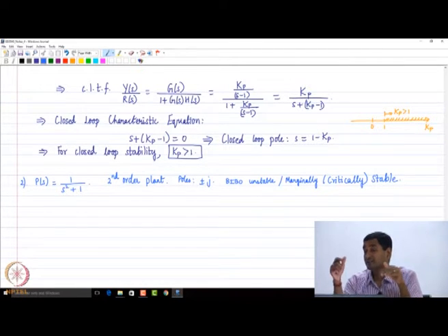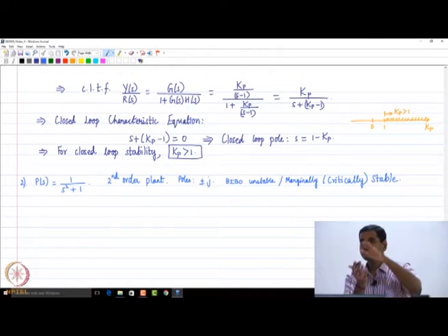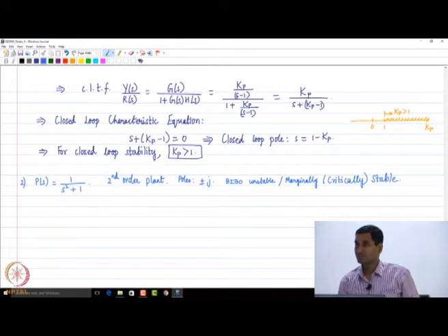Would that car even sell? Can you sell that car? Imagine that you have an automotive suspension whose transfer function is this. Suppose I drive that car on a road at a speed such that the road input coming into the car from the tires has an angular frequency of 1 radian per second. I can always do that, right? If I excite it, what is going to happen? The car is going to vibrate by a huge amount. So I won't even buy that car, because that's going to be very, very uncomfortable.